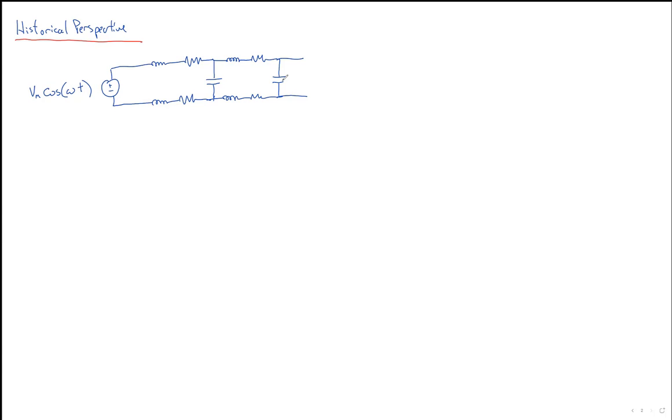If you want to come up with a good model of what goes on with 100 miles of power lines, you're looking at a 300th order circuit. Can you imagine how complex that would be? Just solving the initial conditions would be horrendous. Every new order adds an extra derivative onto the initial conditions. You'd be taking the 299th derivatives, it would be horrible. But there are some things that make this easier.